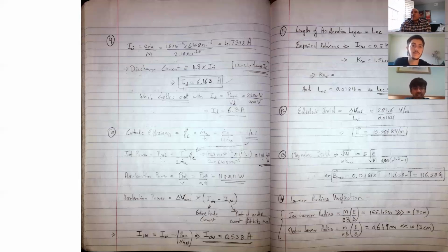That's what I was saying, that some of the ions coming out will want to go to the cathode, naturally, because they're pulled out. So the cathode will shoot electrons towards them, and the electrons will neutralize them. Once they're neutral, they are not affected by the electric field, so they can just move in free space. But then a fraction will escape and hit the cathode. When they hit the cathode, they erode it, and they get very high heat flux on that cathode surface.